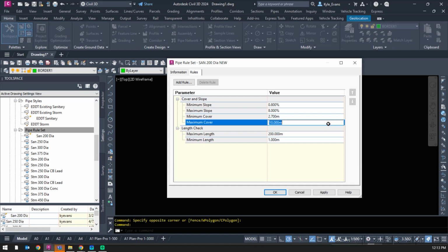That one over there is 22 meters deep. They brought in a tunnel boring machine because it's under a main road. So there really is no maximum depth. Now, I set this for 5 because that's going to be your cheapest design. And really, probably a third of your pipes are going to violate maximum cover. Is that okay?